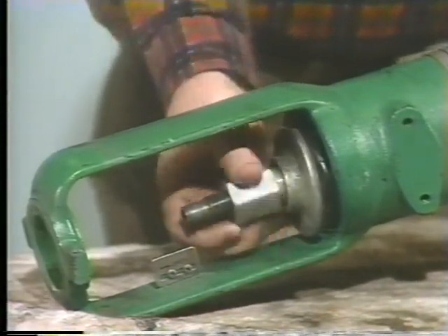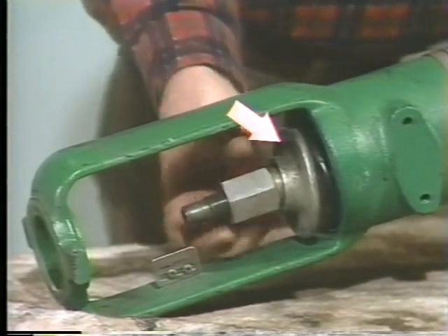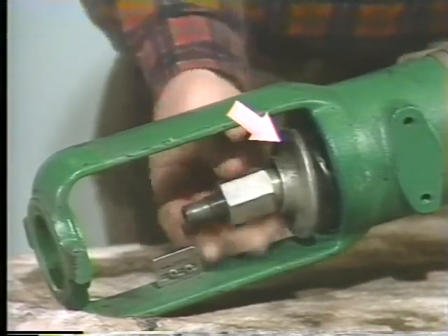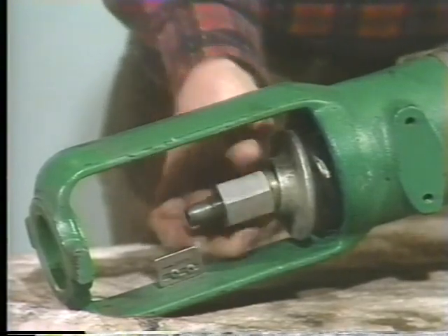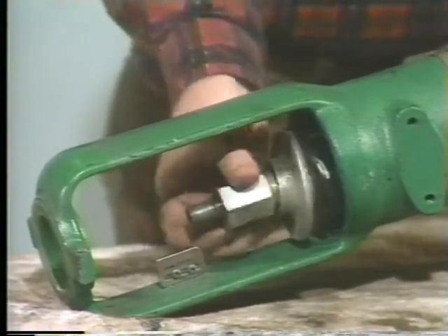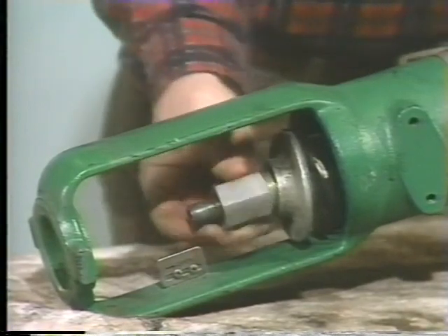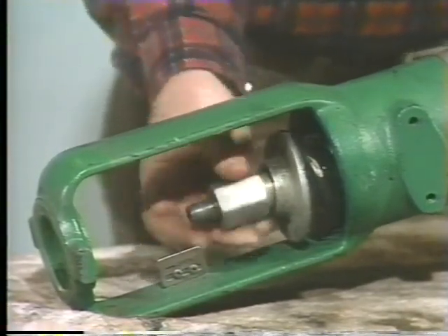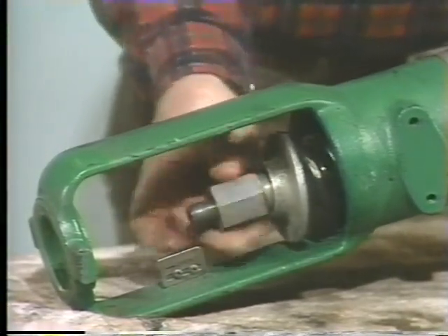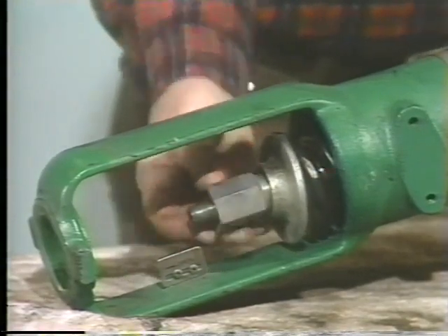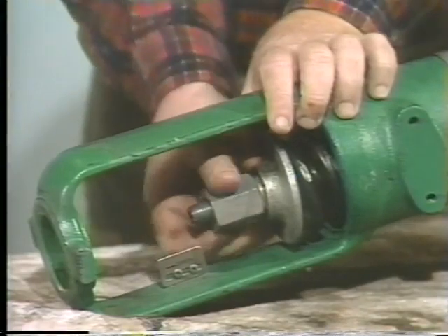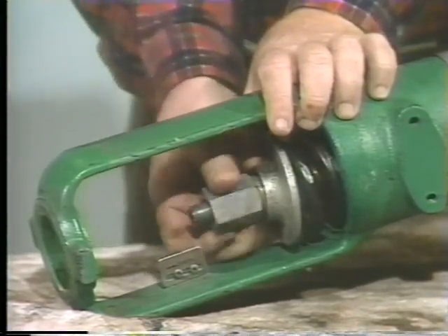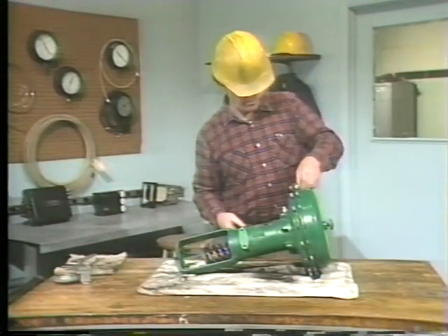The bottom of the spring rests against a solid metal base plate called the spring seat. When the spring adjustment nut is tightened, it forces the spring seat against the spring, compressing the spring. Both the spring adjustment nut and the spring seat have been lubricated as a part of the routine maintenance procedures, so they do not bind when the spring adjustment nut is tightened. Once the spring adjustment nut and spring seat have been removed, the diaphragm casing can be taken apart.